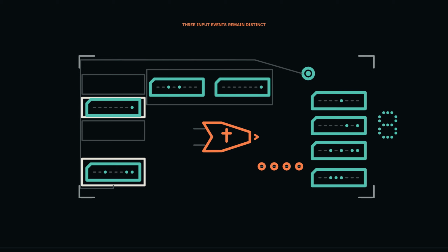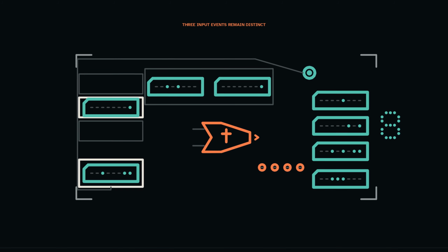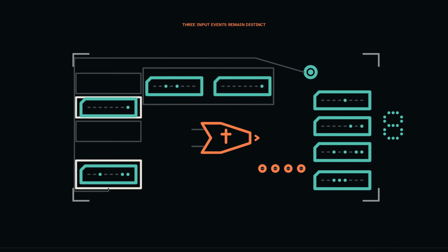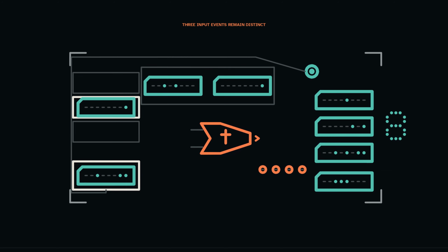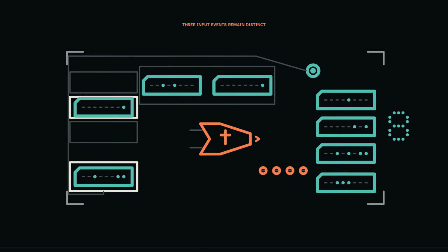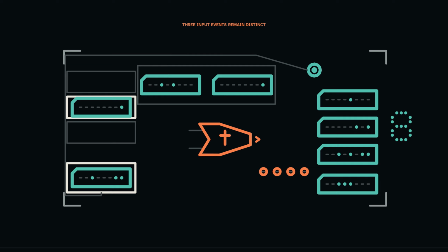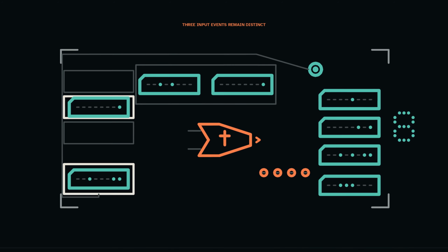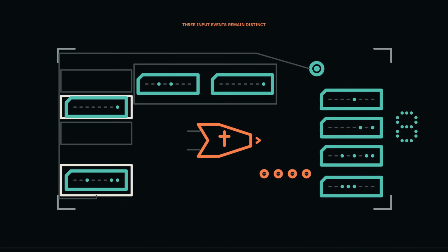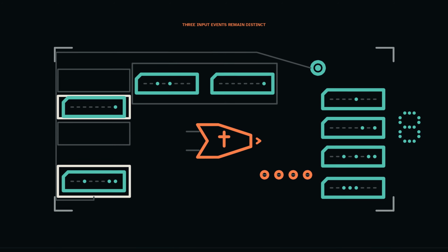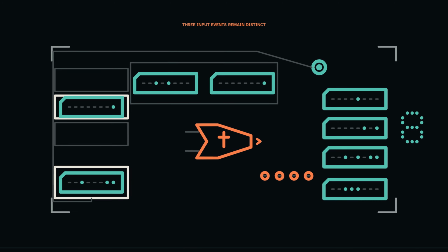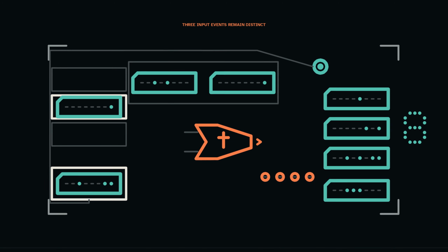Inside the processor, the program counter supplies instruction addresses and memory returns encoded instruction bytes. The controller decodes them into permitted routes. R0 preserves numeric 3. R2 preserves the plus code long enough for comparison to select the supported addition path. R1 preserves numeric 5. Only then does the arithmetic unit add the 2 register operands and produce 8.